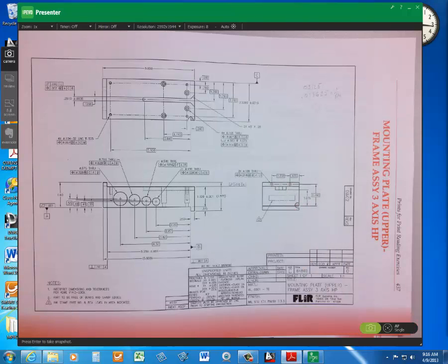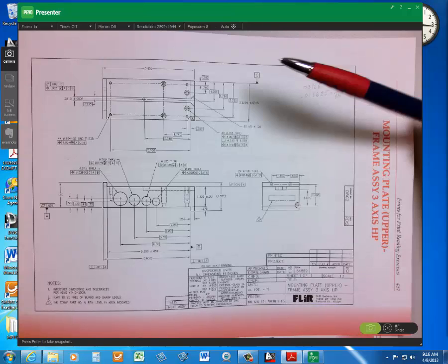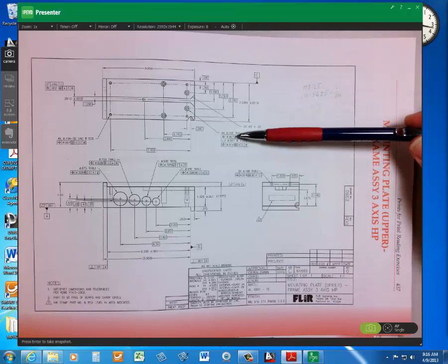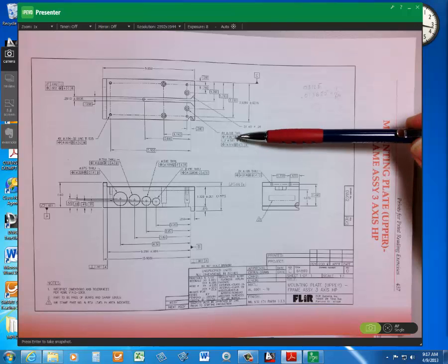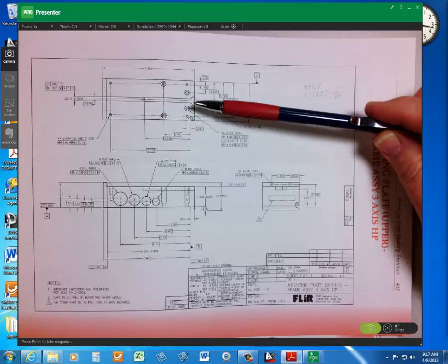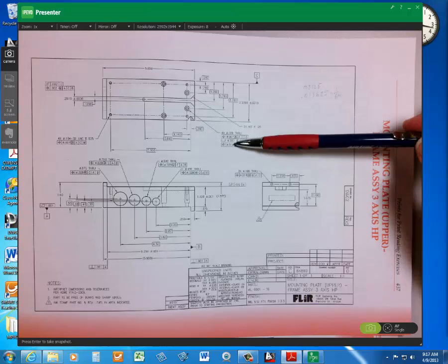The position requirements are tighter for the hole. The hole is listed first right here, and it's 7 thousandths. That doesn't really fully answer why there's a separate feature control frame, except that we want to control the hole differently than we do the counterbore.